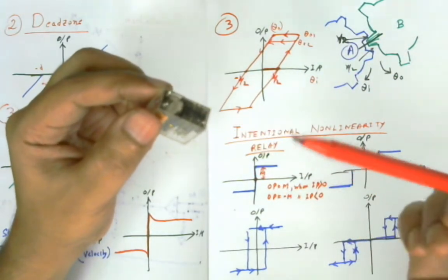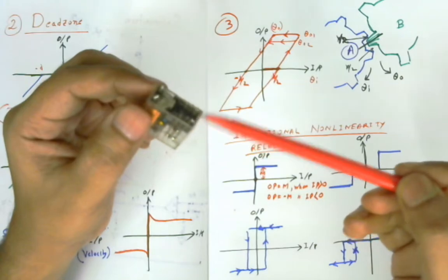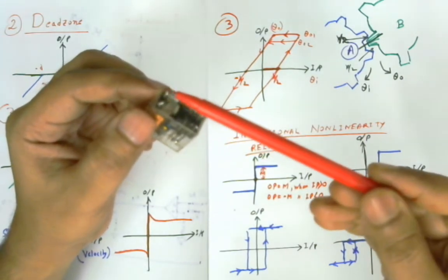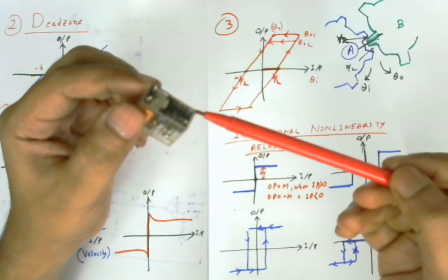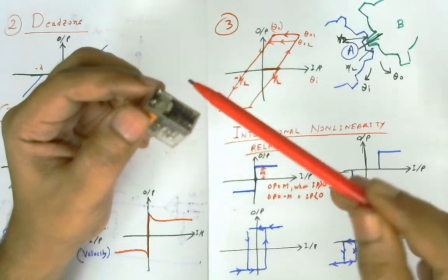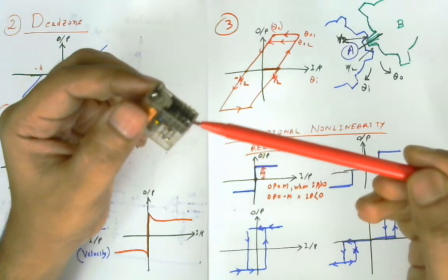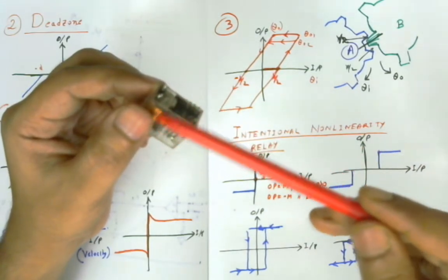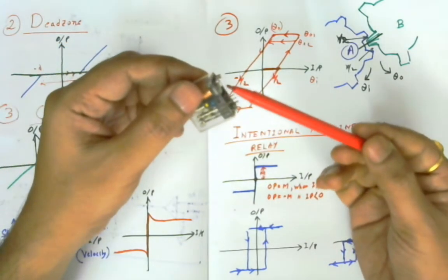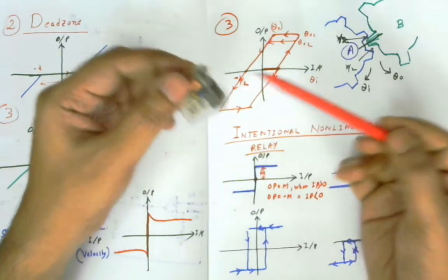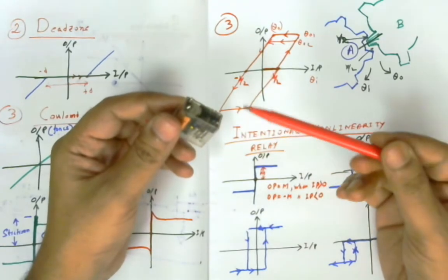So for the purpose of an on off relay, in the case of, say, a motor, you can also connect a motor here, and when the motor is initially off, when the relay coil is energized, the motor is on. The motor may be operated with say 400 volt. You can connect your 400 volt DC supply in this case, if your relay is a DC relay, and the motor is connected to these terminals, but the relay coil requires a very small amount of current to energize it. So the relay coil current required for energizing the relay coil is the input, and the output is what will be passed to the load.